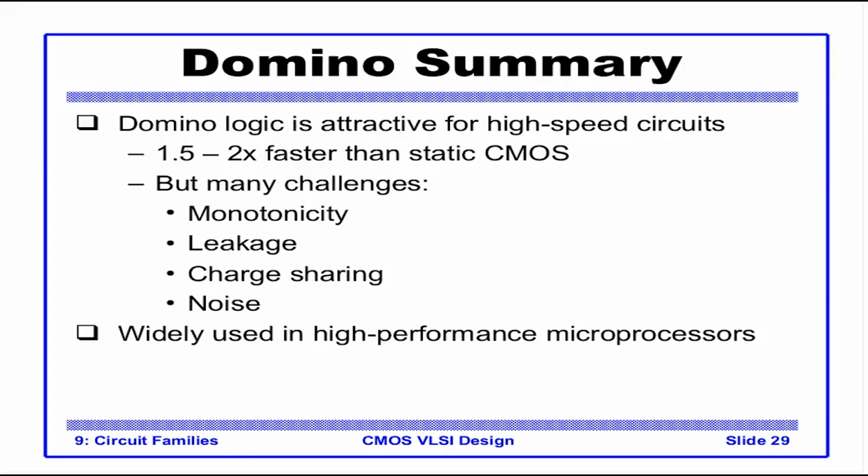So again, I would like to stress the strength of static CMOS. When we go on, we will see standard cell libraries, and all those standard cell designs use static CMOS. So we will not see any domino, dynamic gate, or pseudo NMOS logic. This is more to stress the point that different logic families do exist. They are used for very special circuits where speed is of paramount importance, and to appreciate the robustness of static CMOS.